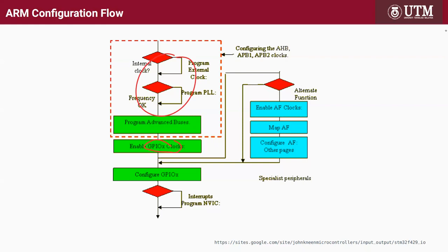So if, for example, I'm not sure, GPIO I didn't check. What can GPIO A do? What can port A do instead of just general purpose IO? Have to check the documentation. So if I want to use it for something other than GPIO, then I have to enable the other clocks also. Okay, and then I have to configure the alternate functions. But if I just want to use it for GPIO, then I skip that part.